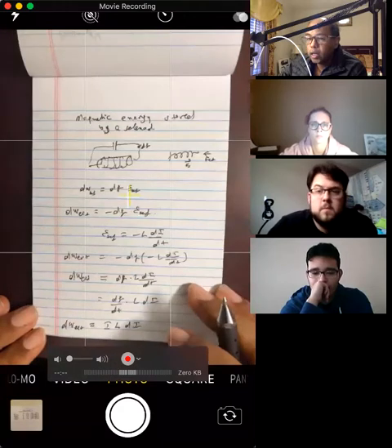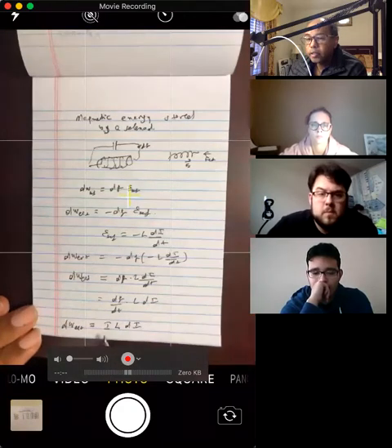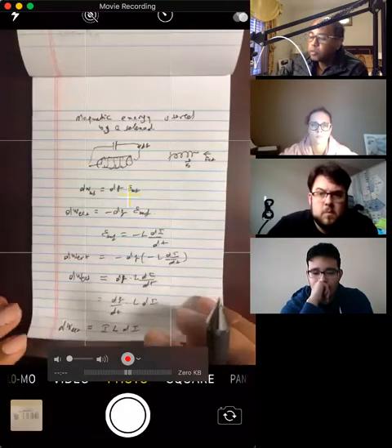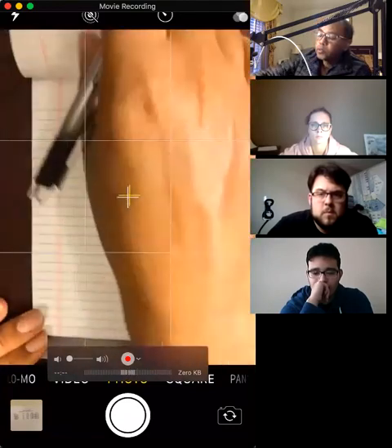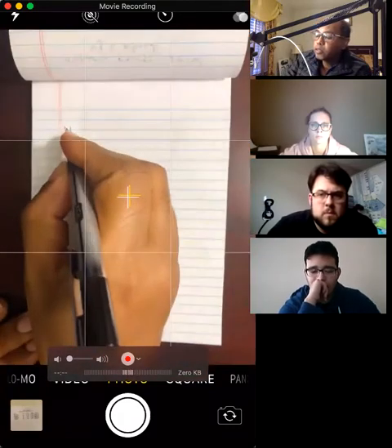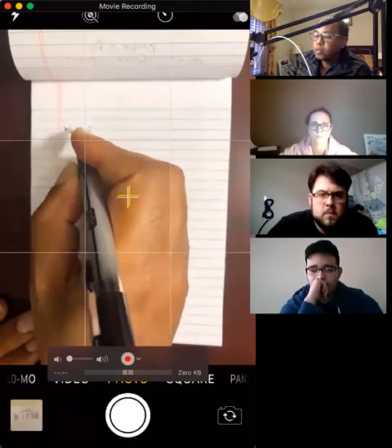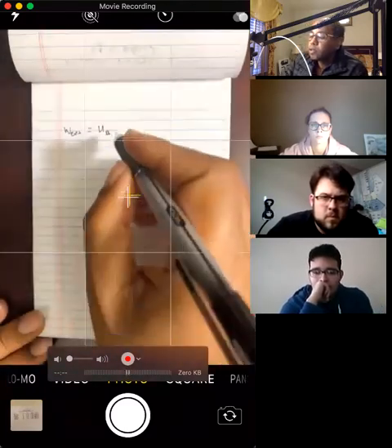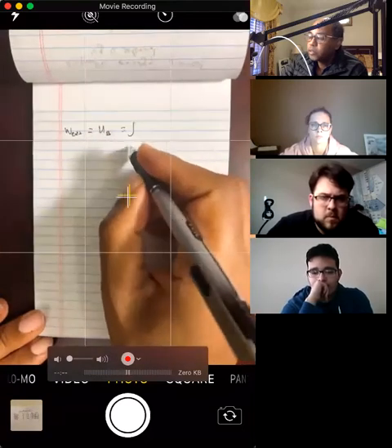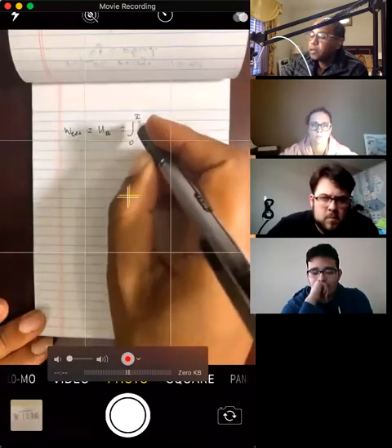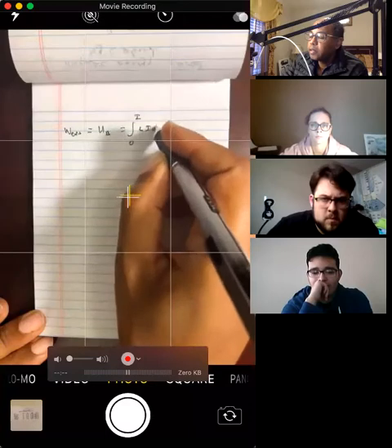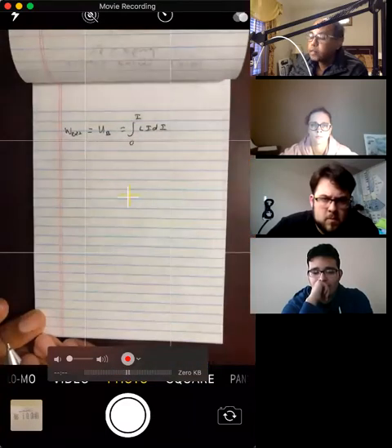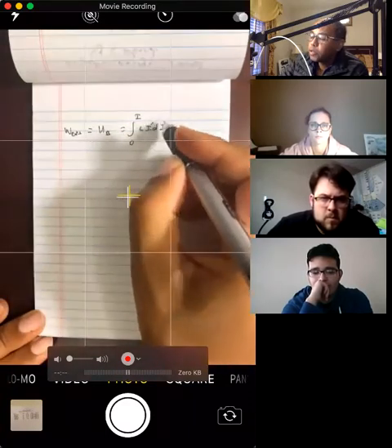Now, for the total energy stored as the current increases from 0 to I, we simply integrate. So the total work done by the external force, which is basically the amount of energy stored in the inductor, is the integral, as the current increases from 0 to I, of L i' di'.